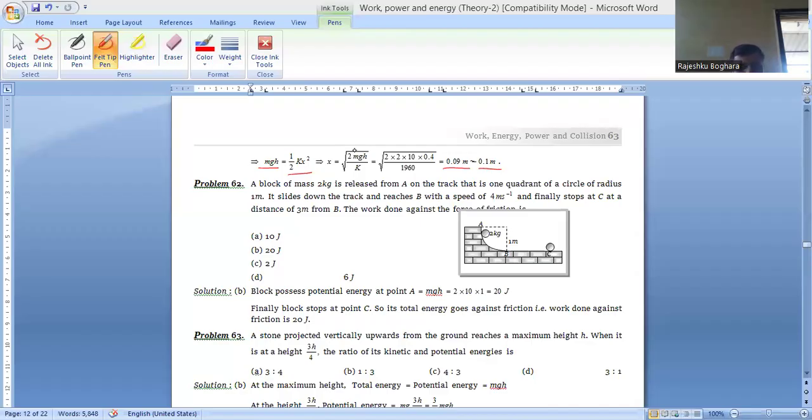On the blade of a turbine, if the height of the fall is 100 meter, h is given 100 meter, then the power delivered to the turbine is approximately. The power is equal to work done by t, mgh by t, m by t given 100, g is equal to 10, and h is also given 100 meter, means 10 to the power 5 watt, means 100 kilowatt. Okay.